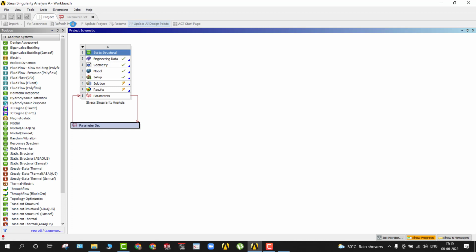So from this particular study we have seen that the model with fillet has the convergence criteria. As you reduce the mesh, the results will also converge. Okay, we have seen how to utilize the charts and the parametric study and the multiple models in a single workbench to run the analysis.